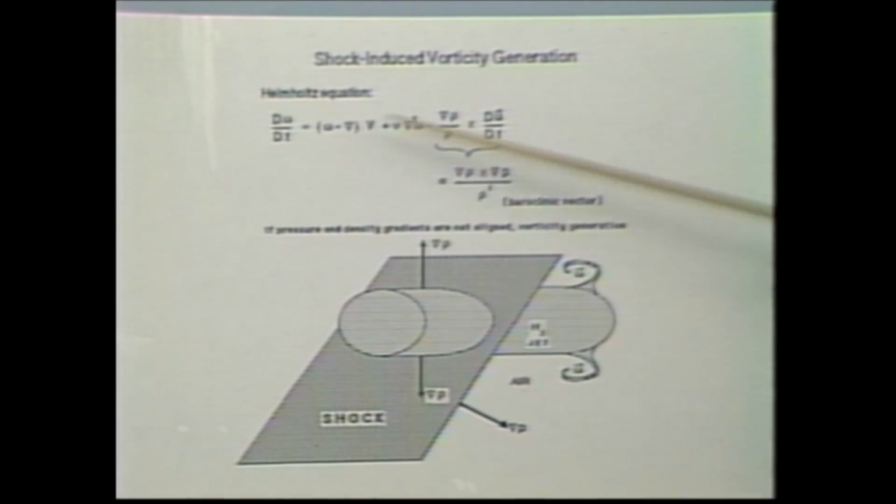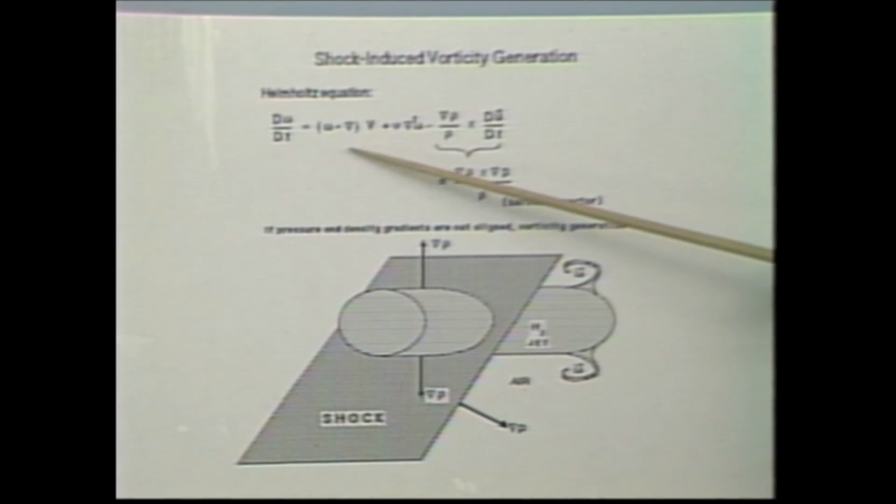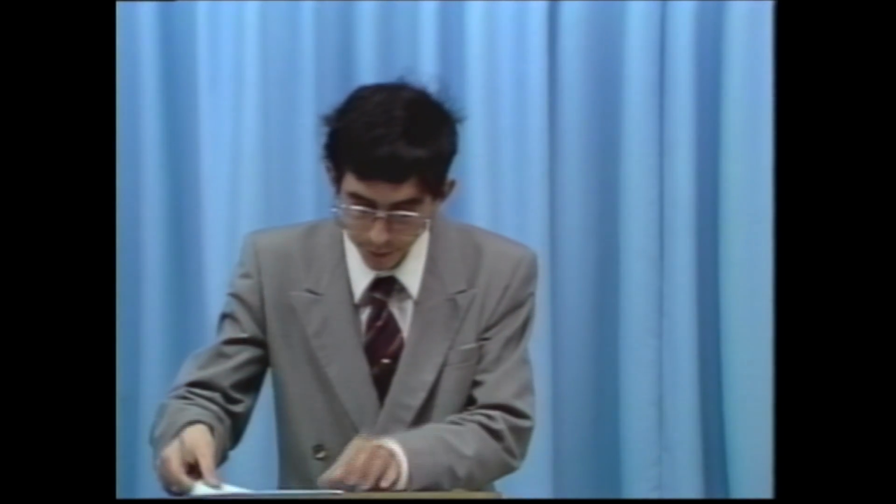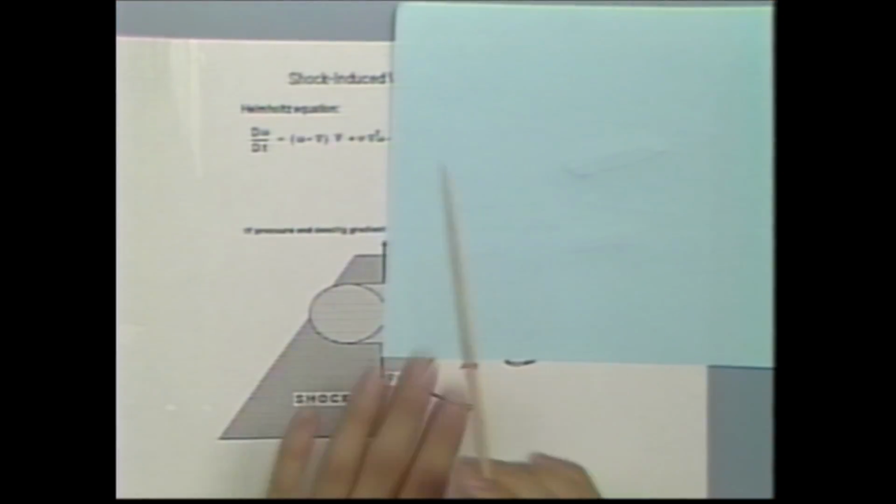Many of you may be familiar with the famous Helmholtz equation. It's the equation of vorticity transport in fluid dynamics. If you're not familiar with it, don't worry about it. All I want to say about it is that the Helmholtz equation describes how vorticity moves in a fluid. And if you're familiar with that Helmholtz equation, you're probably familiar with two terms in that equation. Right? You're familiar with the vortex stretching term, and you're familiar with the viscous term.